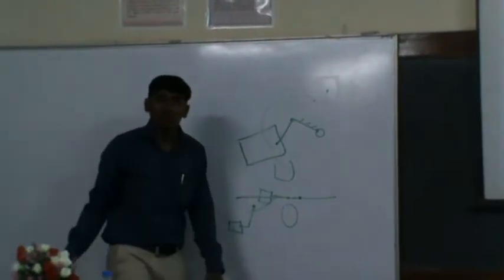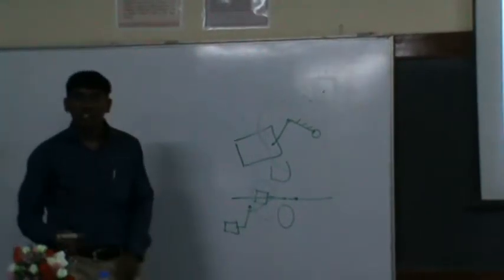Still it will go through this, which we call a self motion, which will exist. So this self motion can be utilized in a number of ways. One of the easiest ways is avoiding obstacles, but the other important aspect of working with a kinematically redundant system is energy optimization, or you can say resource optimization.